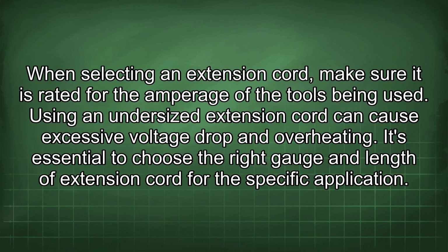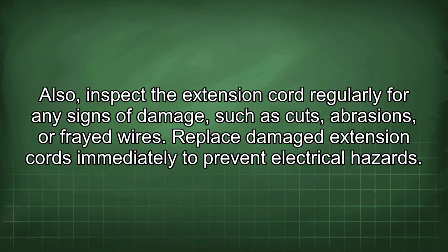When selecting an extension cord, make sure it is rated for the amperage of the tools being used. Using an undersized extension cord can cause excessive voltage drop and overheating. It's essential to choose the right gauge and length of extension cord for the specific application. Also, inspect the extension cord regularly for any signs of damage, such as cuts, abrasions, or frayed wires. Replace damaged extension cords immediately to prevent electrical hazard.